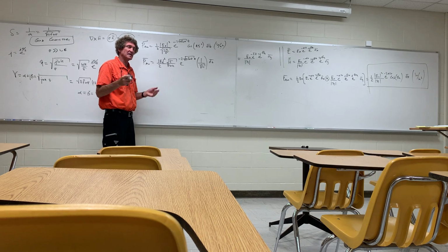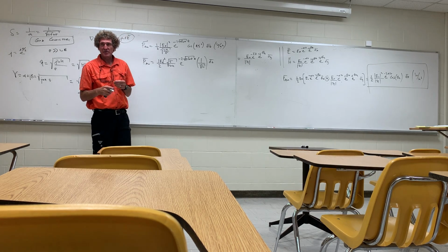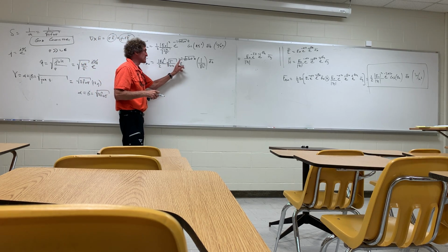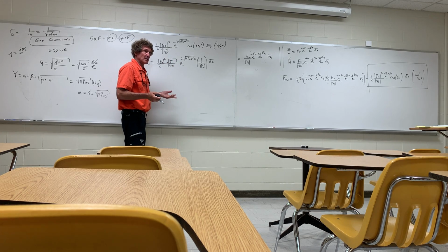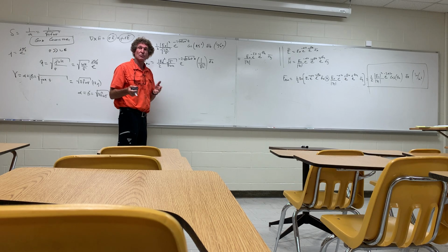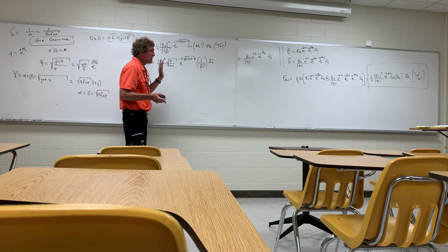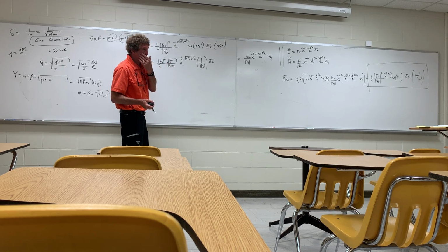After 5 skin depths down, it is about 0. You all follow me? That means this is e to the minus 2 times 5, or e to the minus 10, and that's about 0. It's not exactly 0, but it's getting very close. It's so small compared to the initial power flow that was entering the very conductive medium. You all follow me on this, class? All right, so that's power flow in a good conductor.